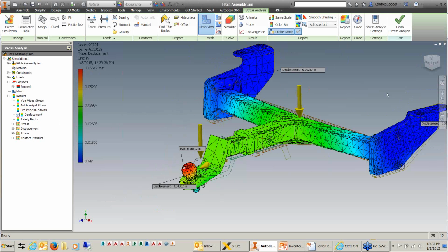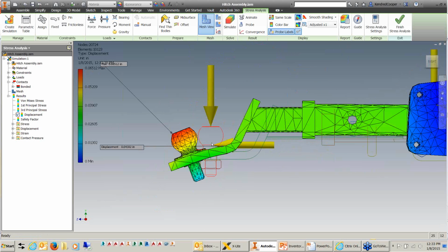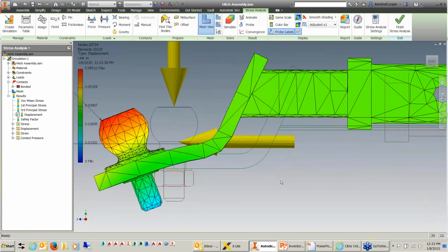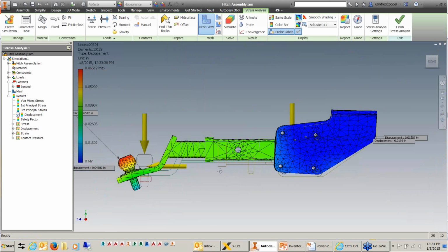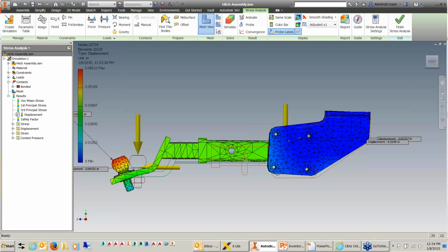The other thing you want to look at, especially with this design, if I look at it from the side, yeah, it's bending down, looks like it's failing, but what I'm also seeing based on the original shadow outline that you see here, the overall angle is bending up. So in a sense, the entire bracket, the mounting, and the main channels of this boat trailer hitch, it's trying to counteract the load that's being put on it.